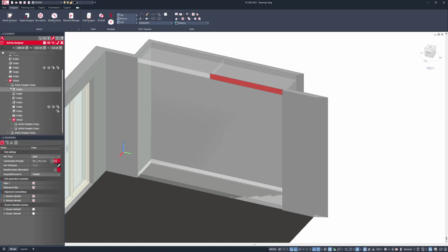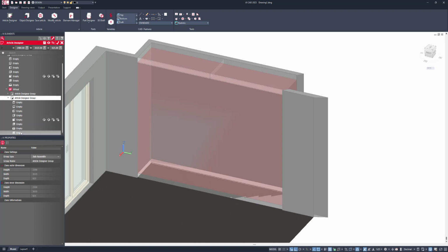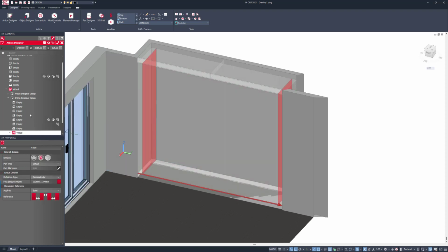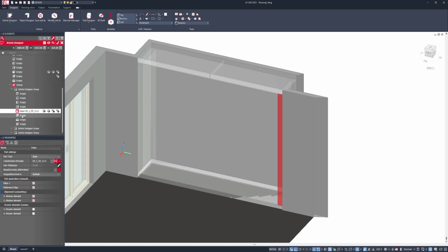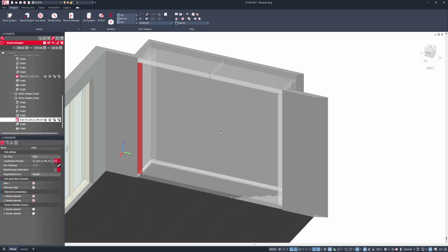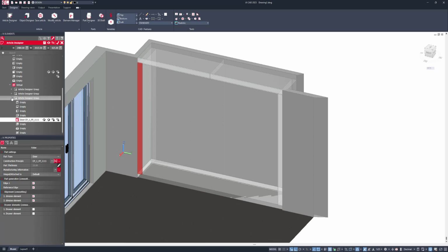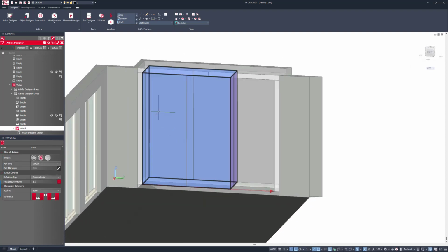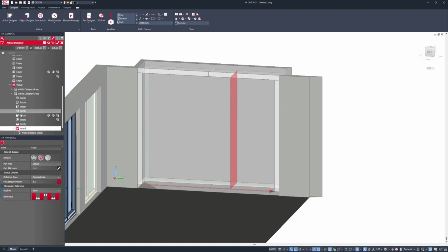Okay, now that I've got that, I need to go into the lower zone and then divide this up again, this time again with a virtual partition, but I'm going to use 100 mil filler left and right. And then in each of those outer zones, I want to paste my filler panel in again. Okay, so I've now got my fillers 100 mil all the way around. And then what I want to do is go to my middle zone and I'll divide this up. So I'm going to divide this again with a partition virtually, this time with a linear division of 2 to 1 to divide that so that I've got a double width zone here.